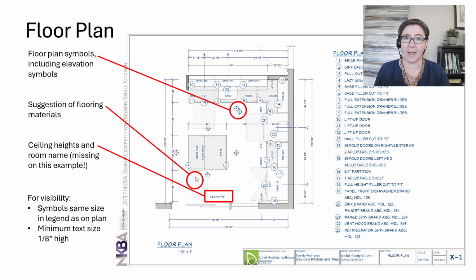Instead, when you're close to done drafting, find an area on your floor plan that is less crowded, shall we say, and in that area, show us kind of a suggestion of that flooring. And the whole point here is to show the direction and how it should be installed. Now, missing on this set, that flooring should be listed in the specification, and then go ahead and tag that specification right where your hatch is.